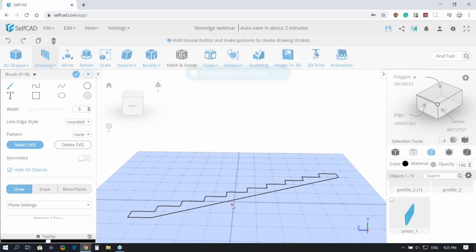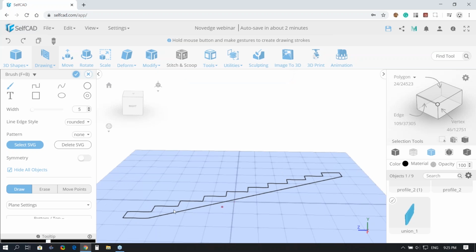So what Freehand Drawing is doing, as I said before, there are tools that have a check mark icon. It works in its own way. This is one of them. It works in its own way because this is doing real-time Boolean operations, as you'll see in a minute. So it's very powerful if you want to trace something and do something. And in this particular case also, this will help me. I don't need to clip that much. You'll see in a minute the way I'll use it.